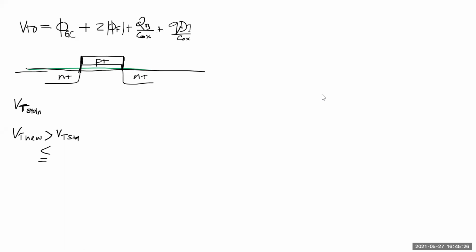Okay, Sandhya Rani says this is less. Okay, Sandhya, why? Give me a reason. Why do you think it'll become less? We take less voltage to form the channel here when we consider P plus, because all the electrons are attracted to form the channel, so we require less threshold voltage.